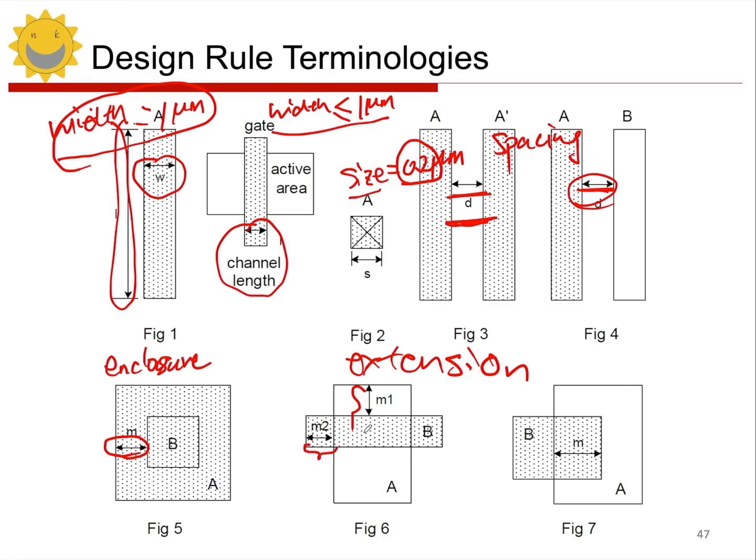Physical verification includes DRC and LVS. DRC checks design rules using EDA tools, comparing the GDS2 layout with rules to ensure manufacturability. LVS ensures the layout matches the schematic, verifying connections with EDA tools using the GDS file and netlist. Design rules define spatial relationships in graphics. DRC ensures design rules are followed, checking geometric shapes in the GDS2 file. LVS compares layout to schematic, verifying device connections. Both checks ensure design accuracy.